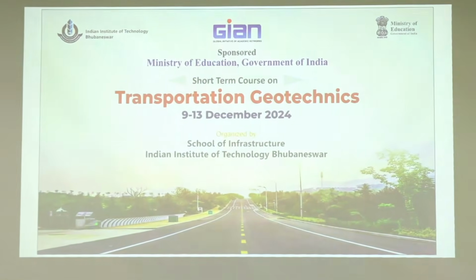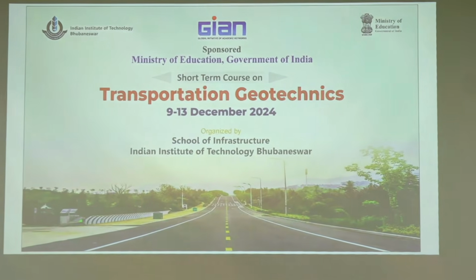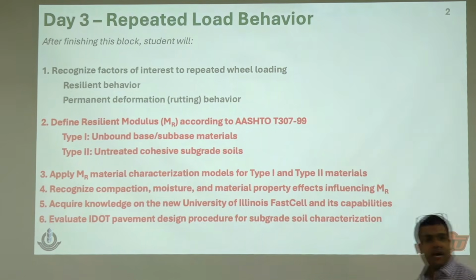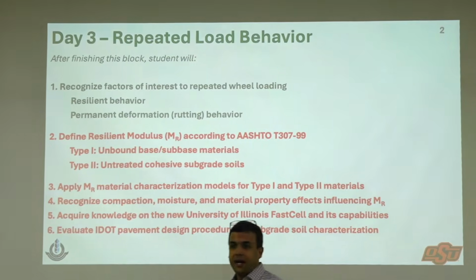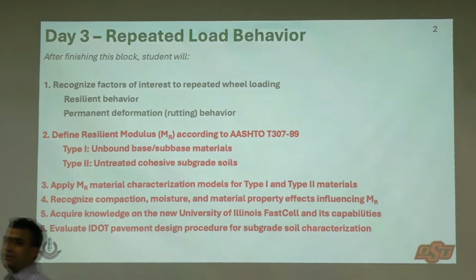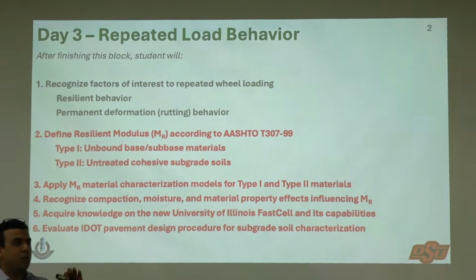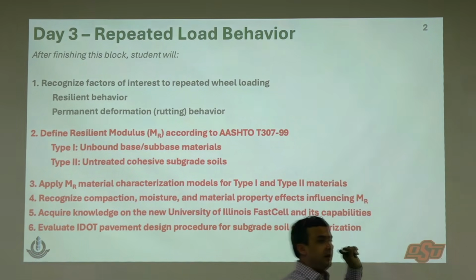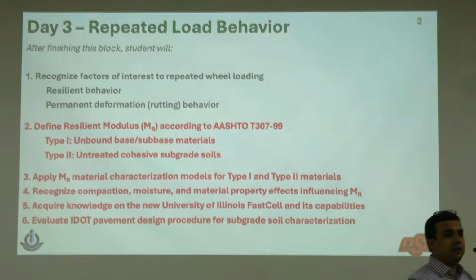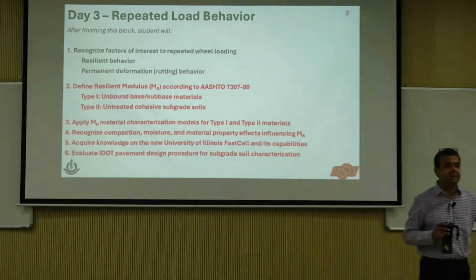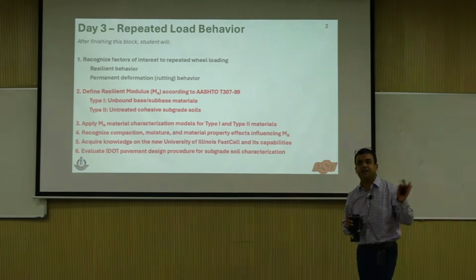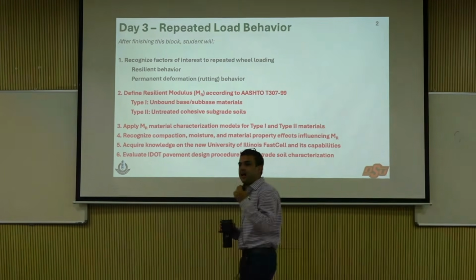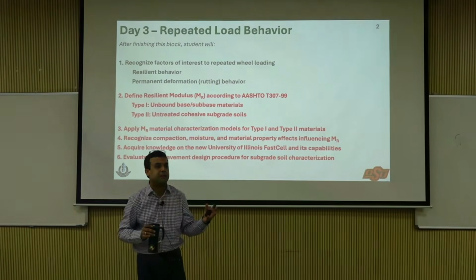We have a very, very, very fun day today. That's what I told you yesterday. We're going to start repeated loading, and today is all about resilient modulus. We're going to go into the details of the procedure, the mechanics, the test procedure. We're going to analyze different aspects, and then we're going to go into resilient modulus model fitting. What is a model? How do you fit your test data to different models? What are the model parameters telling you?